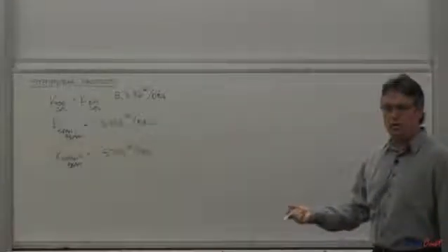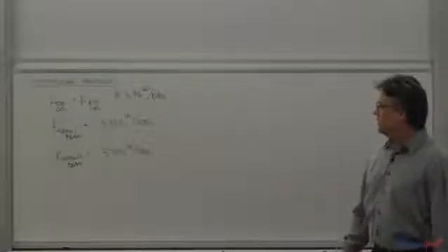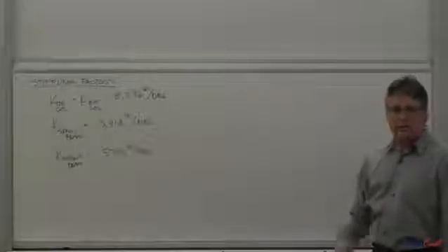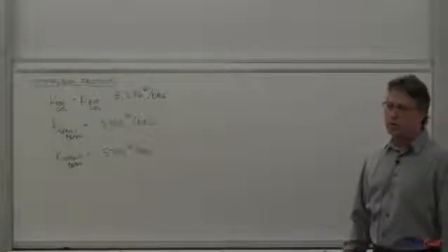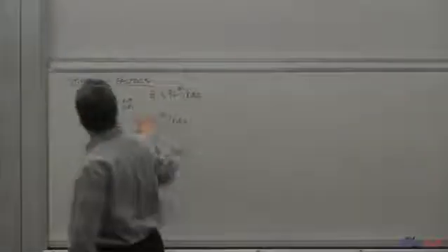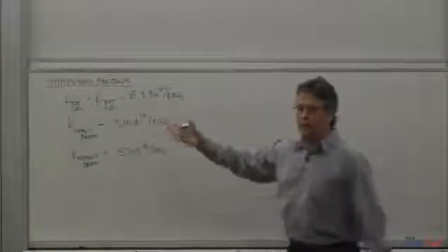I just took the moment that it's required to rotate that 1 degree or 1 radian and converted that, set that equal to x times EI over L and solved for that x value, and that's how I gave you the problem factor. So you have these. I'm not asking you to calculate any of these. This is presented a little bit differently than I'm having you do it. You're actually going to have to calculate it, but I've given you everything.